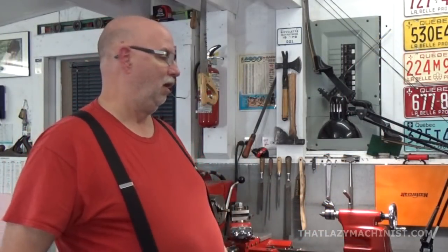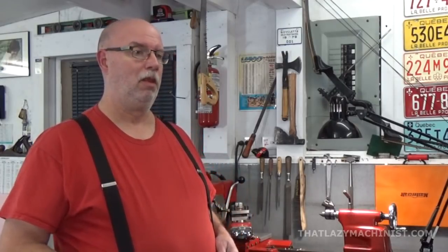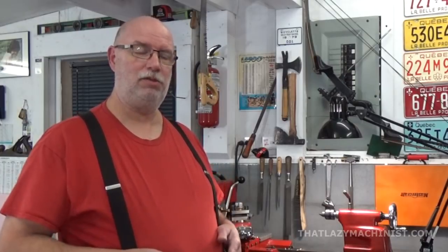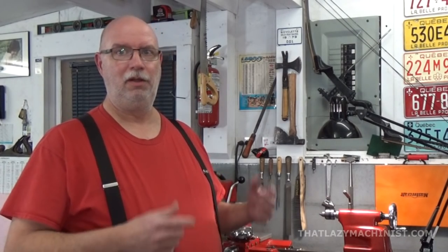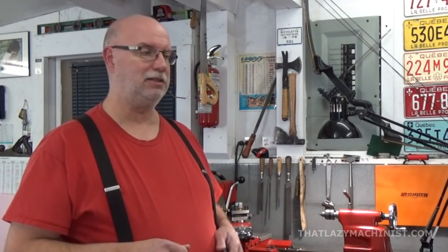Now, as you may know, I'm lazy. And that means that I don't like to make things complicated. Now, my part is a 1/2 inch. I want to touch off the outside diameter and then start from there, setting my 0 on that outside diameter. And that's fine, but my part is nice and round and accurate, but it's in a 3-jaw chuck, so it might be turning a little off axis.